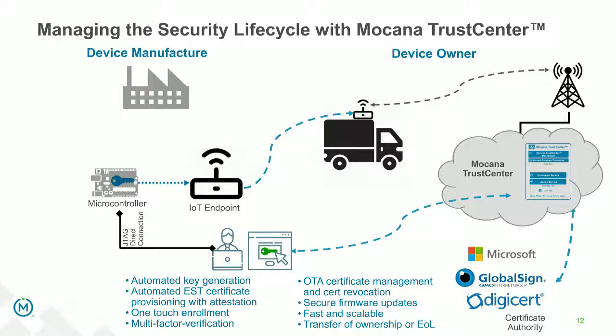So in this case, you could do a local key generation with a secure element with a local trust anchor, or you could initiate a server-side key gen where the keys are actually generated on the server side and then transported back to the device in cases where the devices are resource constrained and may not have the required memory to generate a high entropy and secure key pair. So this basically removes the human element, and just through a configuration file, you can initiate that process of key generation and certification to whatever specification you want.